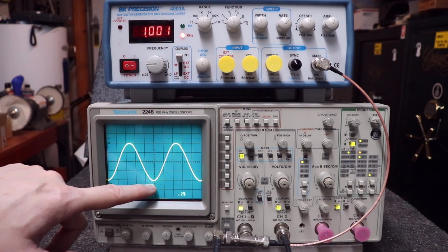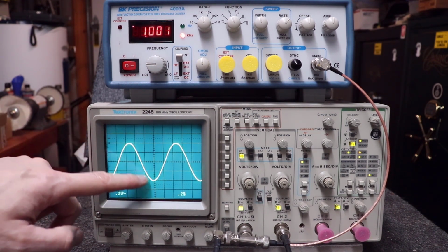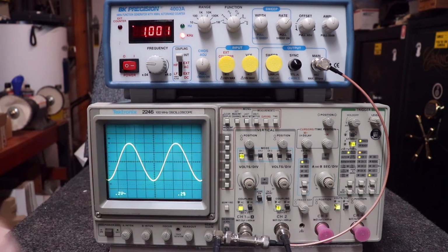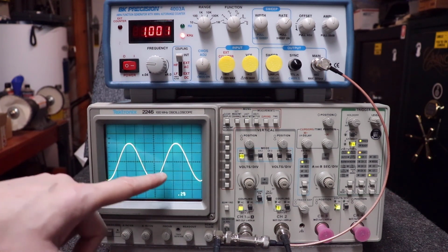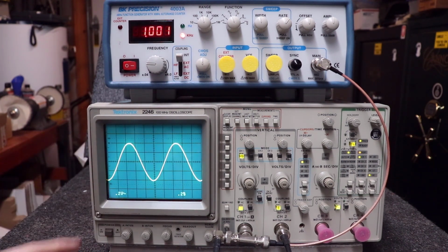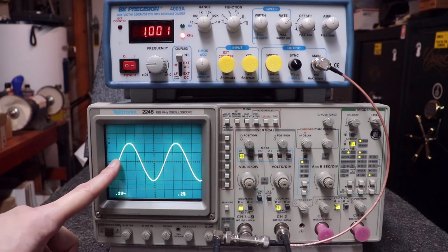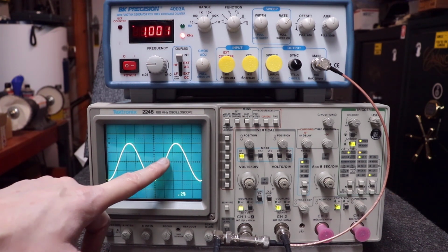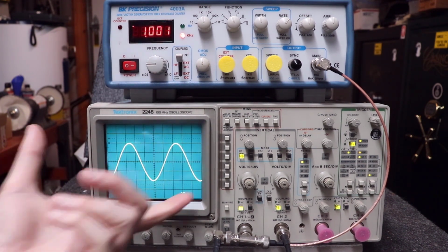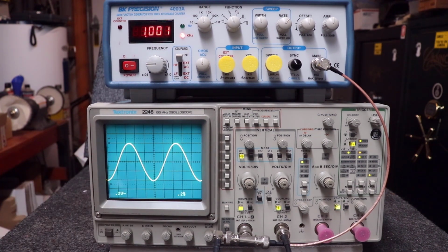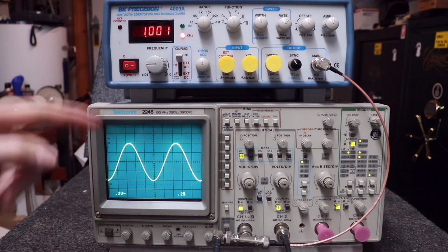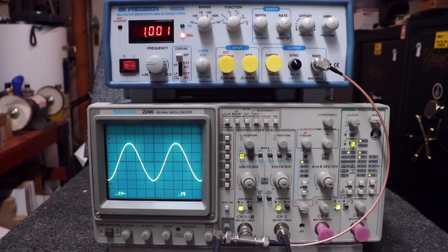Here to here is only half of a repeating signal. It's got to completely come back to the same point. Now I could measure from the bottom to the bottom. That's the same as measuring the top to the top. I could also measure where it crosses the 0 point here and the 0 point here in the middle. And that would help me understand how long that waveform takes to repeat, and we could read that out in frequency. Happens to be happening 1,000 times a second.